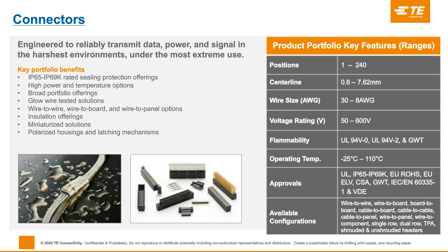And like I mentioned earlier about the flammability requirements, that's very, very needed these days. And as we see the trends go into smaller, more confined areas, you'll need those flammability requirements because things do tend to get much hotter and so forth. So we want to make sure you protect those with the right wires, the right insulation on those connectors. And again, the operating temperature is 25 degrees C up to 110 C. We also have some up to 150 C and higher.